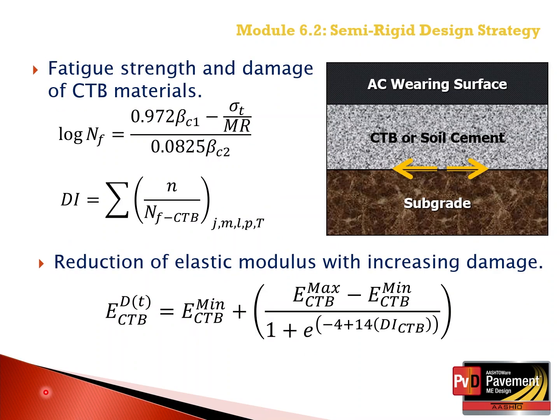Now, the Pavement ME design software gives the user the option to reduce the chemically stabilized mixture modulus to a minimum value that would represent the total damage or destruction of the chemically stabilized layer from the accumulation of damage, as shown in this regression equation. So the reduced E value, or the minimum E value, shown in the regression equation, we mentioned when we had the software open.